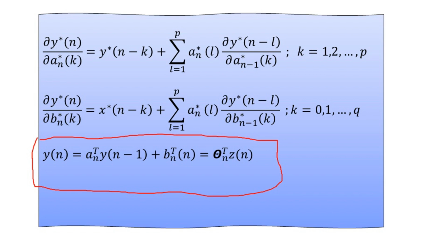Now as we can compare this particular representation with the FIR, that is finite impulse response LMS algorithm, which we have covered in the sixth topic for the convergence of the LMS algorithm, we will find that the IIR LMS algorithm has very slow convergence with respect to the filter coefficients that minimize the mean square error here. Therefore, first of all, we shall focus on the derivatives of the complex conjugate of y